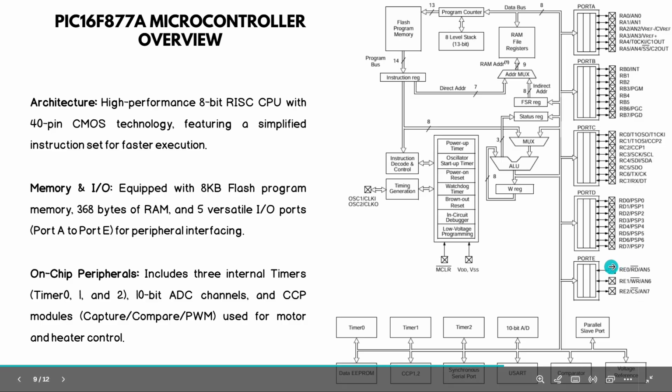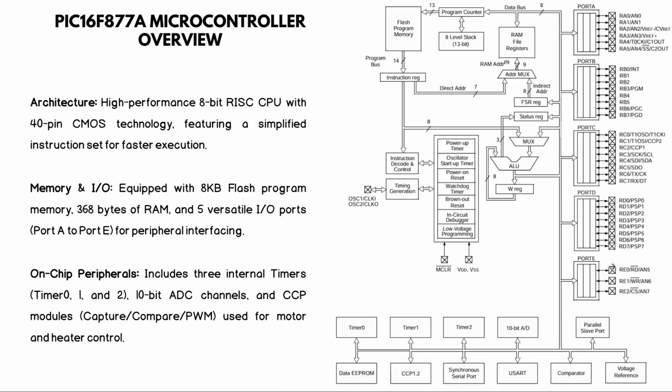Port C is used as the action port for the microwave oven simulation. The pin is used for pulse width modulation. You can use this to control the speed of the DC fan, representing the heater.